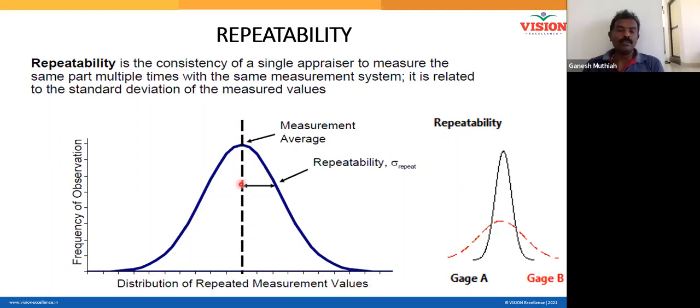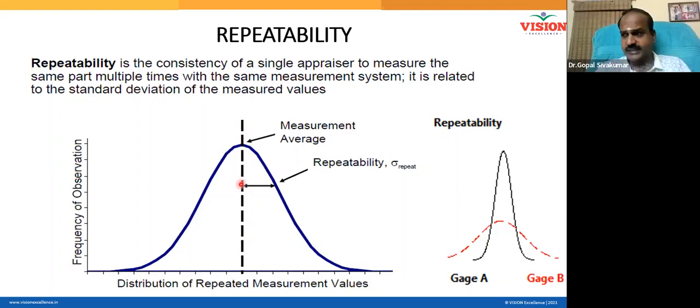Now, using the same data, I can calculate the standard deviation. Here is the standard deviation. You all know standard deviation, right? Square root of summation of x minus x bar the whole square divided by n minus 1. And now, the whole lot of readings that are going to come out from a particular operator will definitely fall in this population, in this curve. Definitely the sample will be within the population. Am I right? All the sample data, 100 data, will be inside this curve.